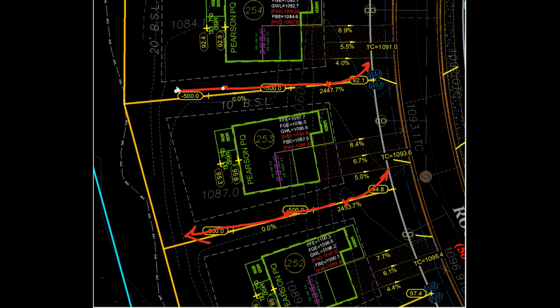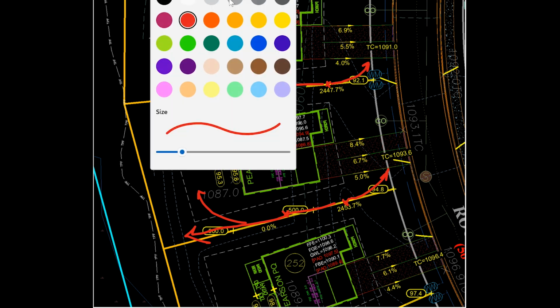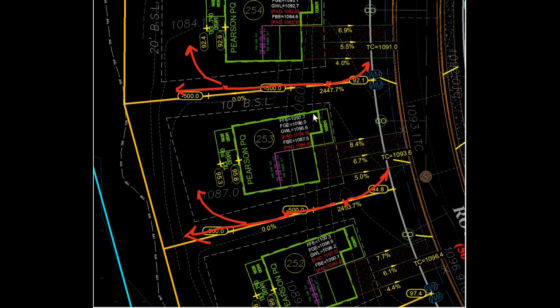And so looking at 253, 254, I have a thought that this water will most likely just dump into the back of the lots. I think that's a pond or a creek back there. But sometimes what will happen is they'll put a drop inlet, say for example, at the rear of the lot, 254, 253, and they'll put an inlet back there to make that water go into the inlet instead of having it fall off onto a slope, a rear slope.